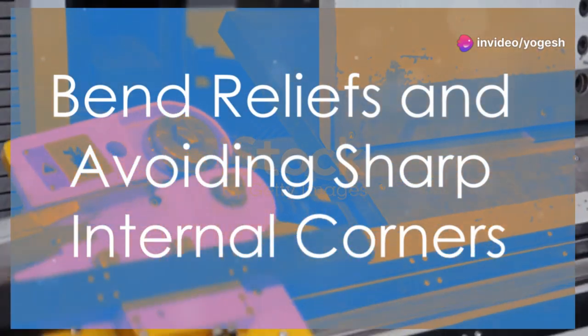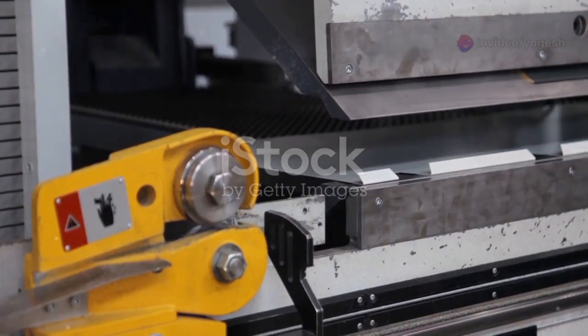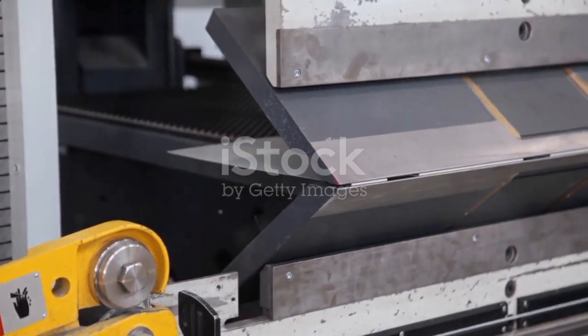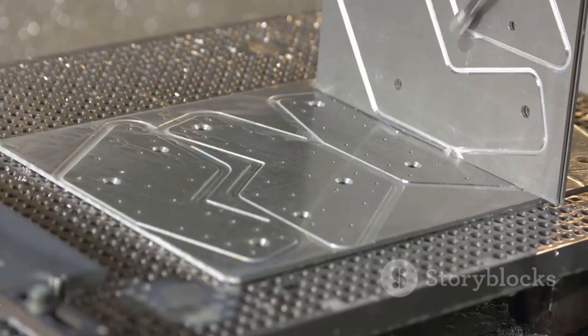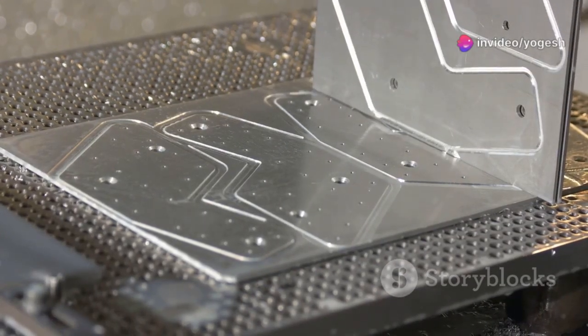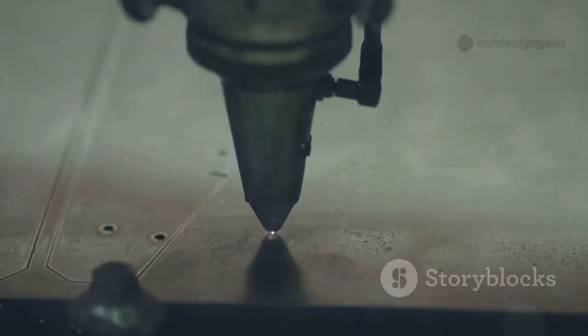When you bend sheet metal, the stress isn't limited to just the bend line. It actually spreads out into the surrounding material, which can lead to problems if not addressed. That's why relief cuts are so important. These small notches at the edges of bends help prevent tearing, bulging, or unwanted deformation, especially at the corners where stress is highest.